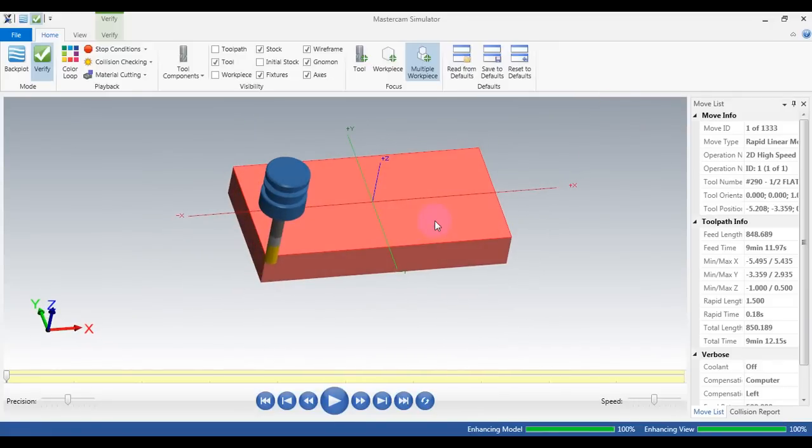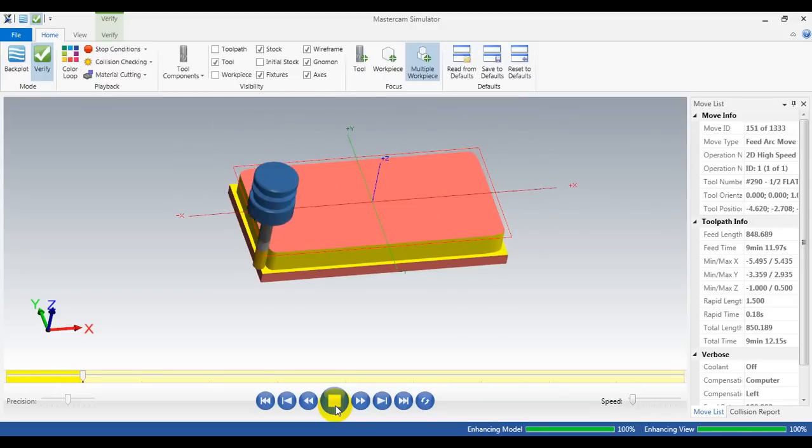The first toolpath is the dynamic mill with the from outside strategy. That means the tool will cut the part from the outside. When we cut from outside to inside, I reduce the speed a little bit. Okay, and run it. You can see it runs like a champ.